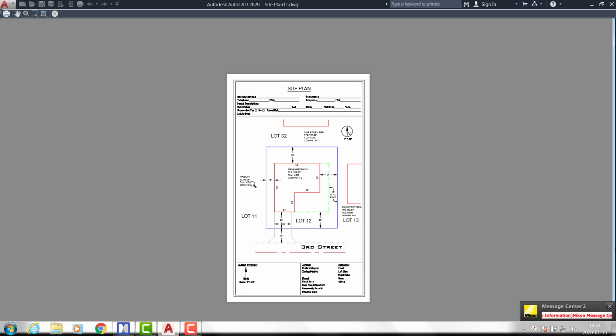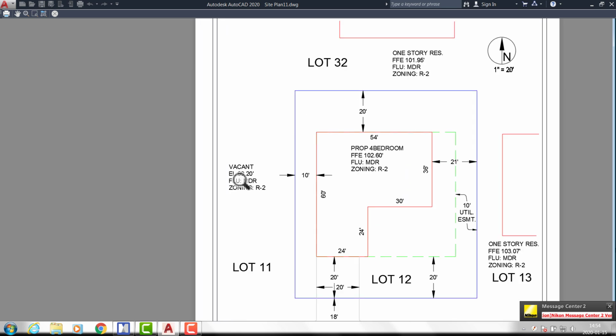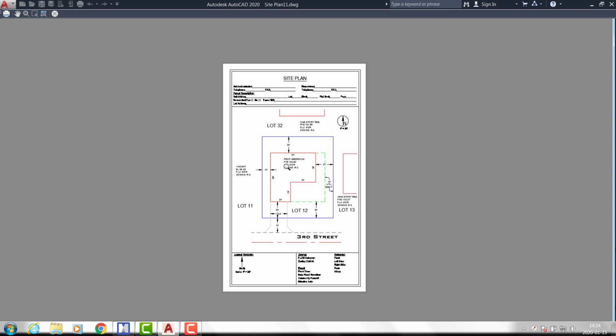So the same is applied for text height. When you say that the text height is going to be 0.1 inches high, then when you plot that to the PDF, that's the output that you're going to see when it's actually printed to a piece of paper. Is the height of the text will be 0.1 inches. So that ties into our annotative scaling.